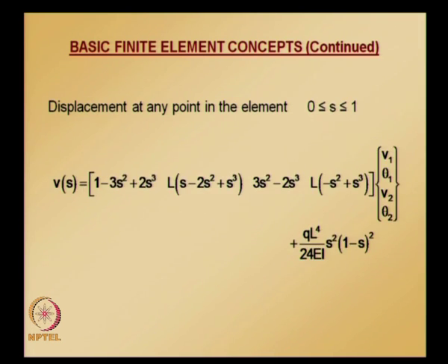So for displacement, the nodal values you get from the finite element method are exact, but at any point in between we need to add the fixed end solutions.